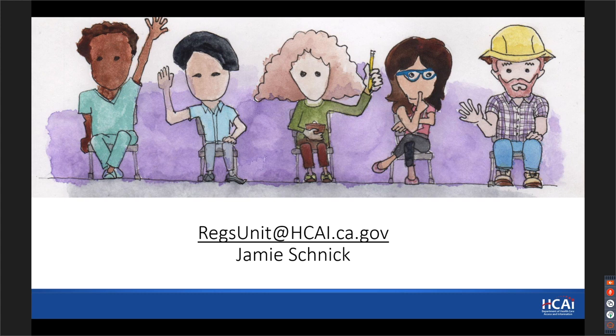Awesome. Thank you, Jamie. Next question reads, does the transformer have a dedicated space requirement on top? No, it just needs ventilation space requirements. Thank you. Next question, is a GFCI switch allowed to protect the receptacle serving equipment? A GFCI switch? Yes, absolutely. That's kind of what I was talking about, where you pull out the GFCI device separate from the receptacle. Right. Thank you.